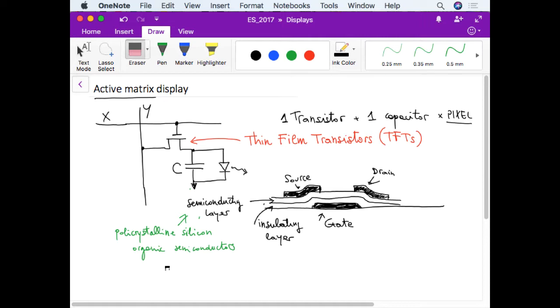The typical common screen that uses this type of solution is the so-called AMOLED. You probably have heard it because it's a commercial name. The AMOLED, for example, is used on the Galaxy S series by Samsung. And also, for example, the iPhone 8 started using the AMOLED. So until 7 it was an LCD screen, and from the 8 it's AMOLED. And AMOLED means active matrix OLED. So the architecture is the active matrix architecture, a DRAM-like architecture, and the LEDs are organic LEDs.